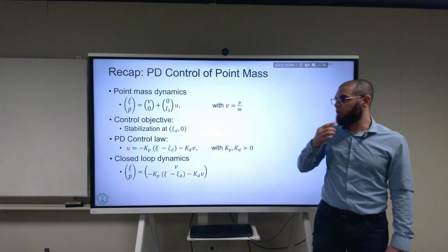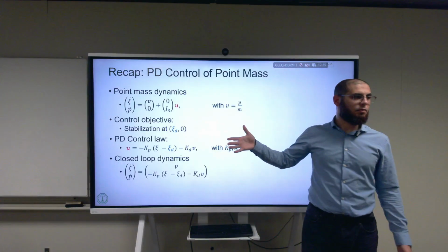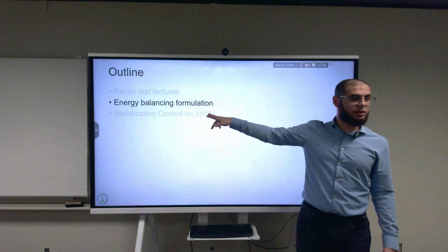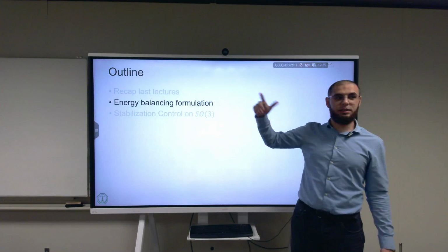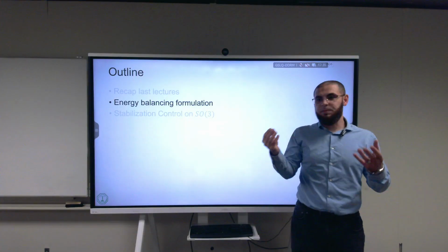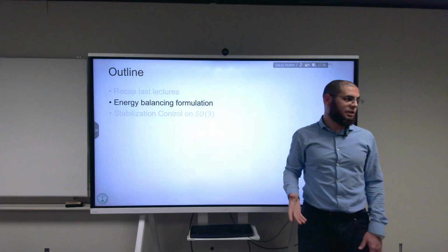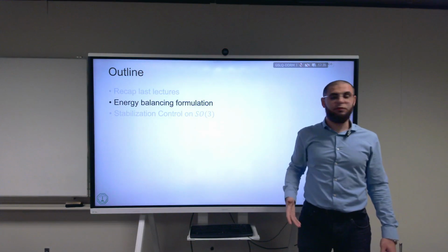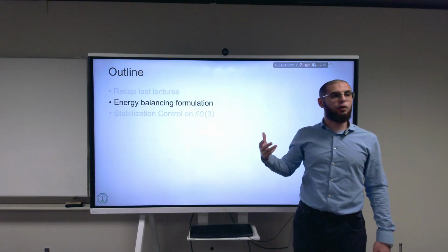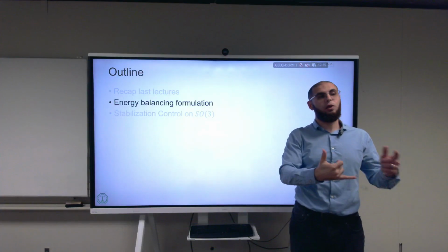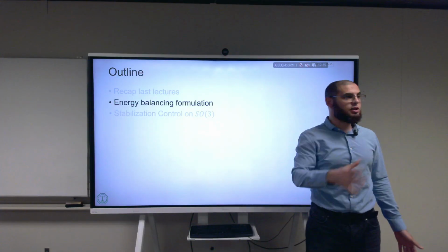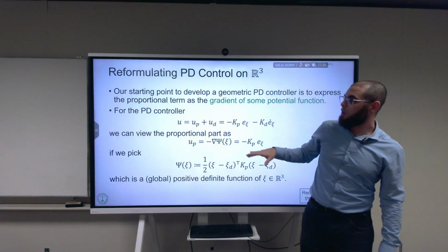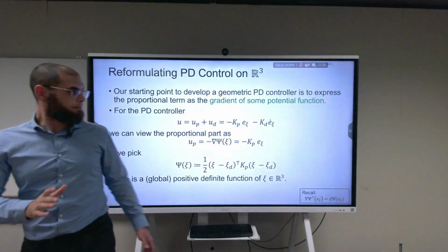That's a very good question. So I'll rephrase the question: why PD? What was so special about the PD? Hopefully, when we generalize this, you'll actually see why. Actually, the answer to your question is in this part. We're going to reformulate the simple PD controller. It looks very innocent. Any bachelor student should know this PD controller, and there are, of course, more complicated versions of it. But here, we're going to be reformulating it in a way that will enable us to generalize it to SO3, SE3 and in general. And it will partially answer this question: for mechanical systems, why is the PD very special? Okay, so this is the way we're going to be reformulating it.